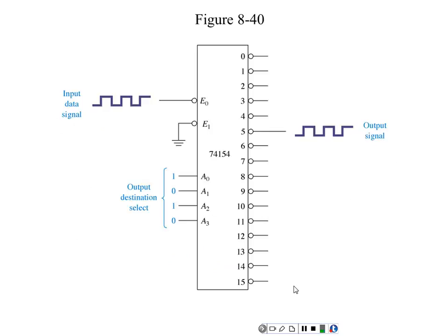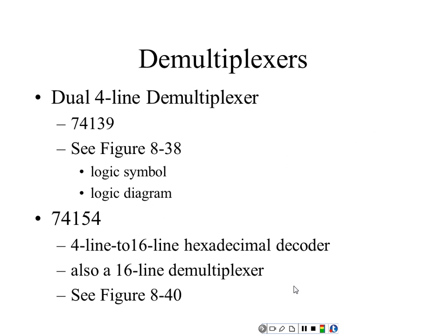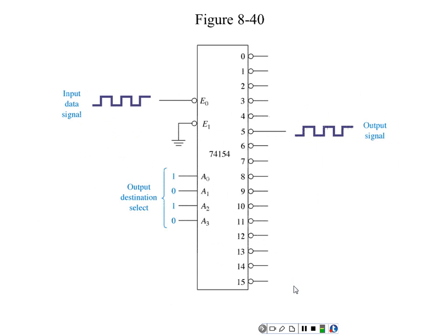Oh, okay. So this is a 74154. This is a decoder. And we could use a 74138 too. I thought that would probably be the one they would get us to, but this is okay. So we got this E pin. What's E? Enable. Okay. So we got this E pin, and notice they've got the other E pin connected to common all the time, so that one's true. So what we connect up to the E pin up there is the multiplexed signal coming in. So this right here is multiplexed.